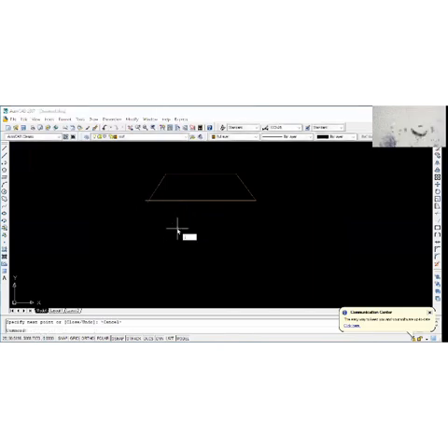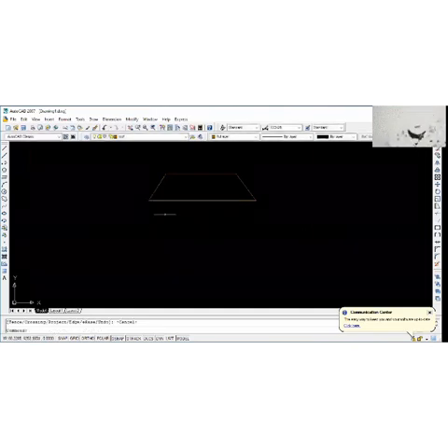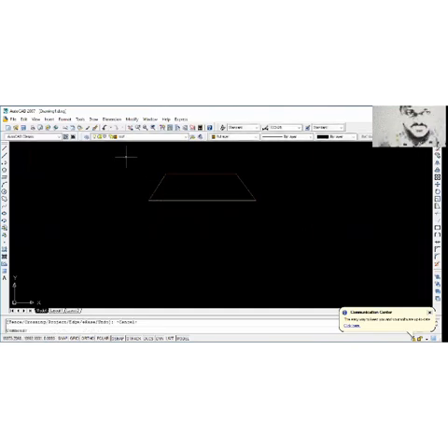And then let me quickly TR enter to trim. Then right click, and let me trim this place. Let me trim this place. That is it. Then escape. So you can see the color of the roof is in line with what I have here. So now don't forget, I already used a thickness. So it's supposed to be thicker than this. So it means I have to come to line width, left click on this. So you can see now that it's thicker because I already gave it a thickness of 1 millimeter.